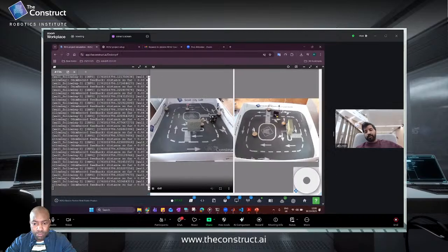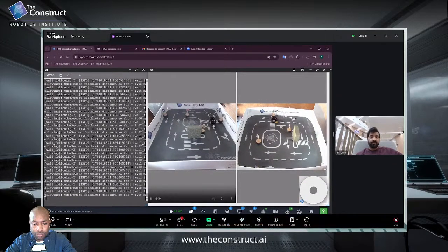Previously the speed was higher, so the processing time of the robot was slightly slower. So today I reduced the speed by 1/3 to 2.5 meter per second, and now it is slightly slower, but it allows the robot to process everything and adjust itself.